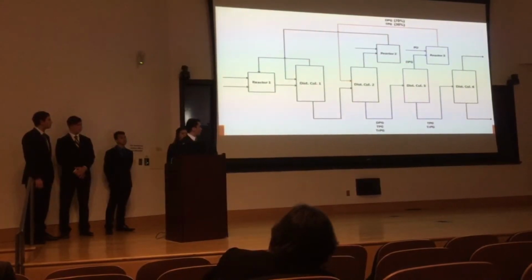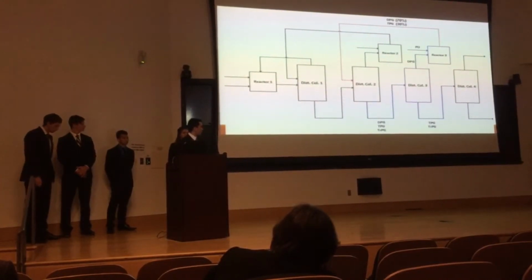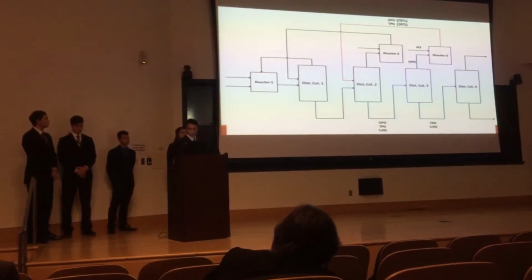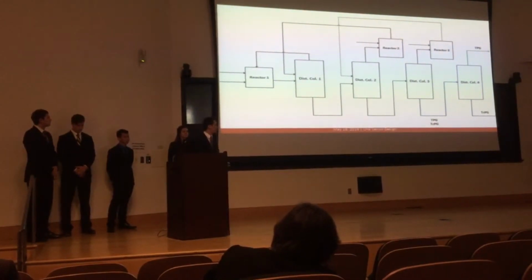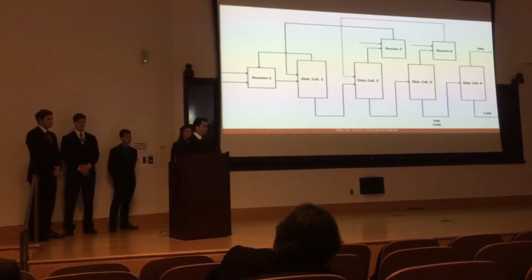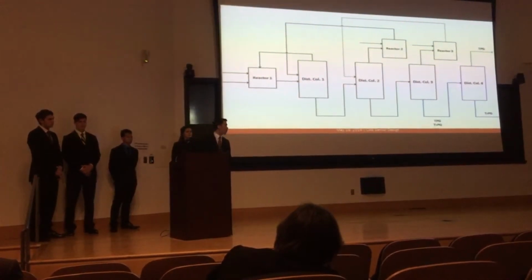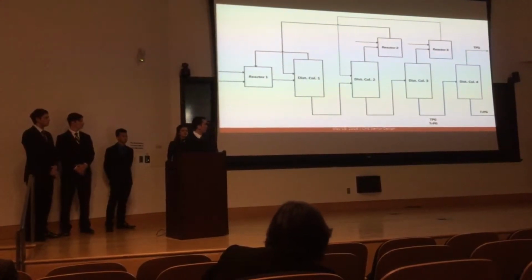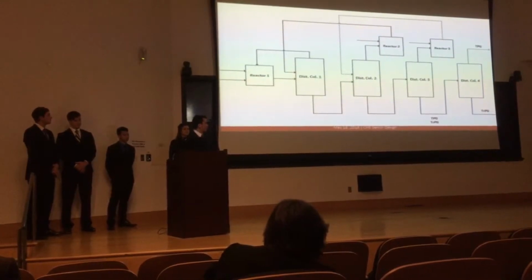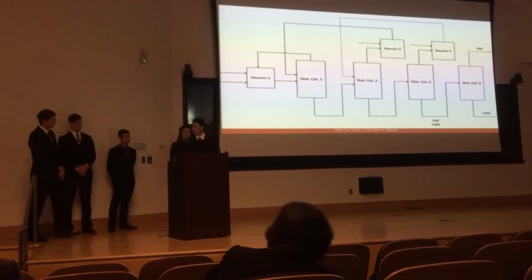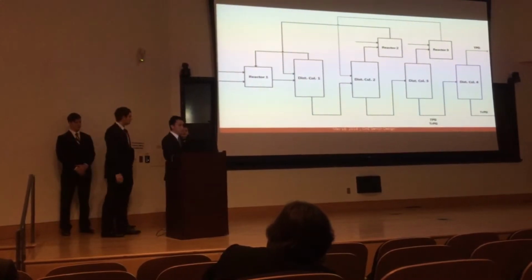Lastly, the bottom product is then fed into the final column, number 4. On the top we have our desired product, which is tripropylene glycol, and on the bottom we have our byproduct, which is tetrapropylene glycol. By using Aspen simulation, we find that the purity of the product is about 99%. And now Cass will talk about the optimization of the process.